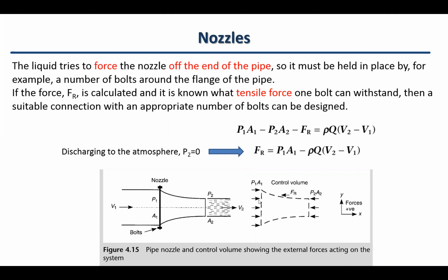Now, this is the force applied here, and it has to be in this direction because it transfers the force to the bolts. So FR is shown in the reverse direction in this way. As I discussed before, if you by mistake choose the force in the reverse direction, you will see FR calculated with a negative sign. Anyway, for this FR on the left-hand side, we can easily calculate the tensile force that we need to design the bolts for.